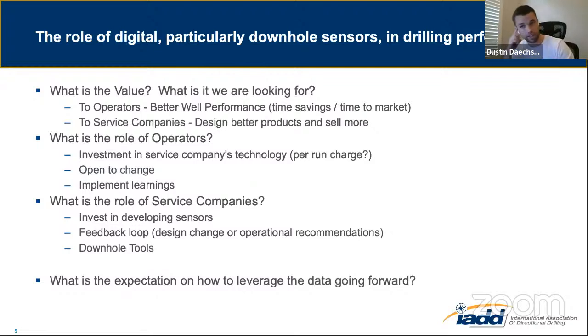Okay, well, I can give you my perspective on downhole instrumentation and where I see the value case. To me, it really revolves around two types of buckets. One is real-time decision making. So we see that there's a particular vibration excitation mode, and we address that, whether it's axial bounce, lateral vibration, or perhaps even stick slip.